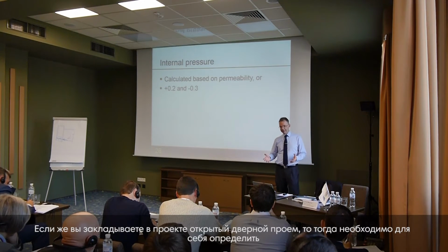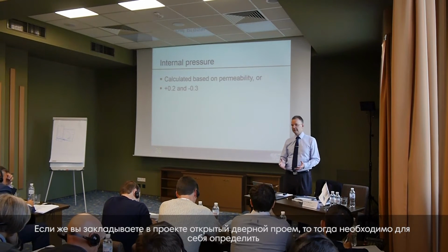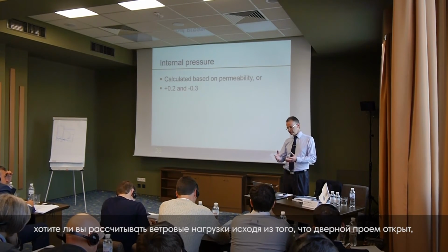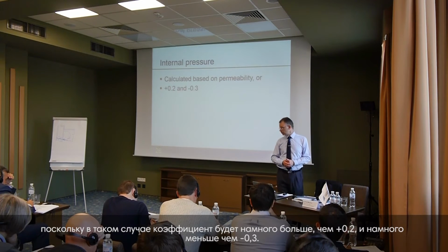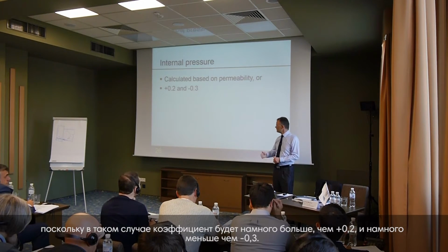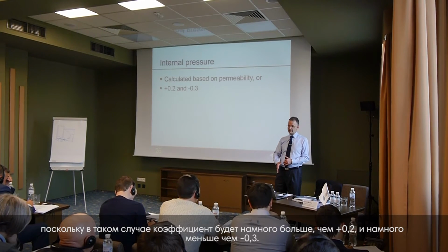If a door is open, then you need to make a decision. Are you going to carry out the design assuming that the door is open? Because then the internal pressure coefficient will be much greater than plus 0.2 and will be much less than minus 0.3.